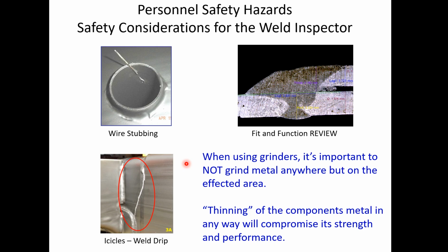We have to be careful of this, and make sure nobody gets hurt inside our plant or their plant. And don't forget, under almost all conditions, there's an E-coat involved, so those people are affected here too. We're probably not going to get a very good E-coat unless we knock that off of there. Most people will take a grinder and grind that to make sure it's gone, with the utmost care not to thin the material on either side of the weld, please.